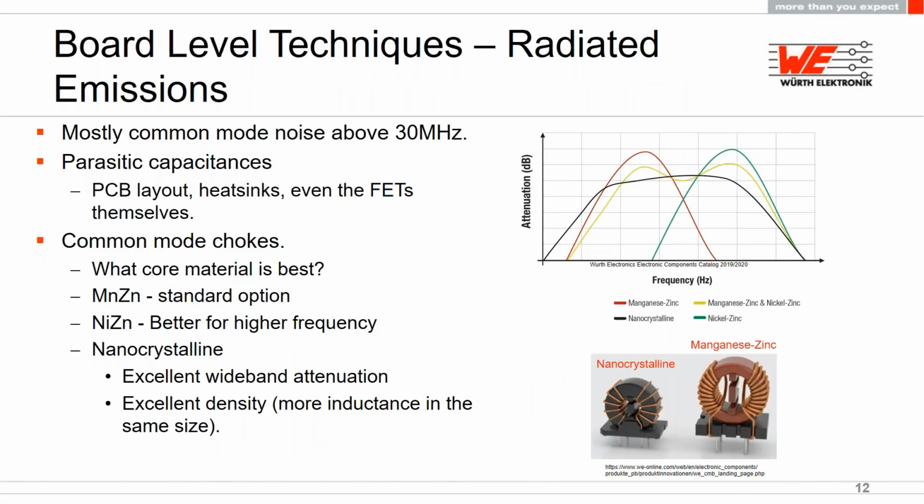So once you're done with conducted emissions, the next step is to do radiated emissions. These are related, believe it or not. In my experience, I've seen a lot of headaches be removed if you do conducted emissions testing in your own lab, pre-compliance testing done seriously, because a lot of these fundamental frequencies that are down below 30 megahertz will cause issues with harmonics up above 30 megahertz, which is now in the radiated emissions band.